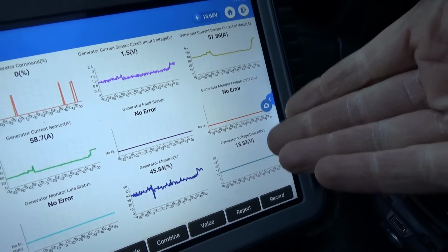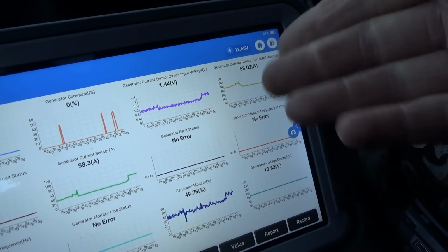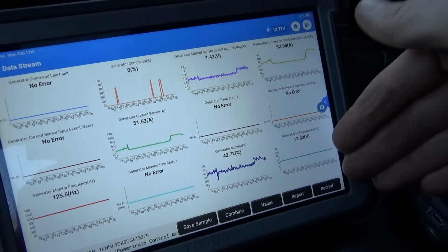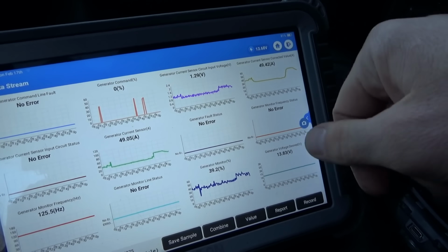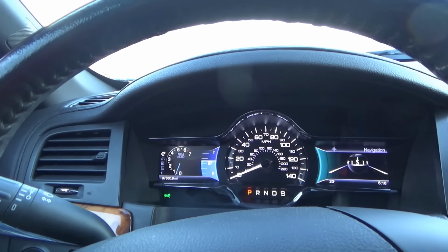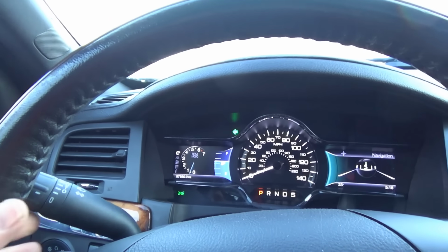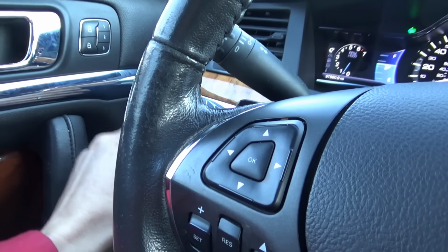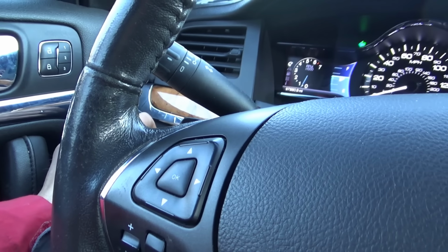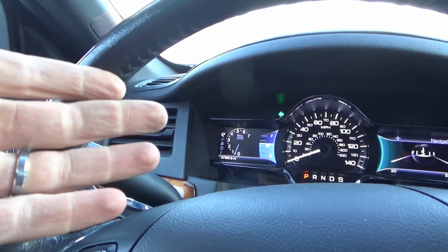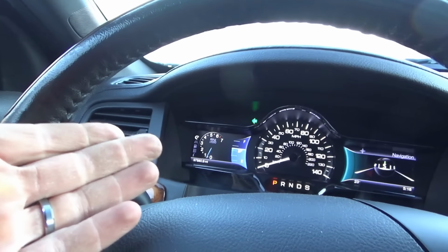So by design, this thing is supposed to maintain 13.8 volts, not 14.5, so that was an experiment, but this is normal operating voltage, 13.8 at the DLC, which agrees with the desired voltage. That's fine. And everything seems to be good when our lights are on, even the parking lights. So that's, I guess, a problem. If your lights are off, you shouldn't be flashing fast.